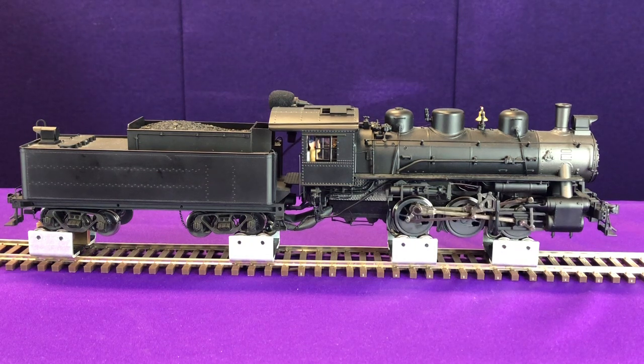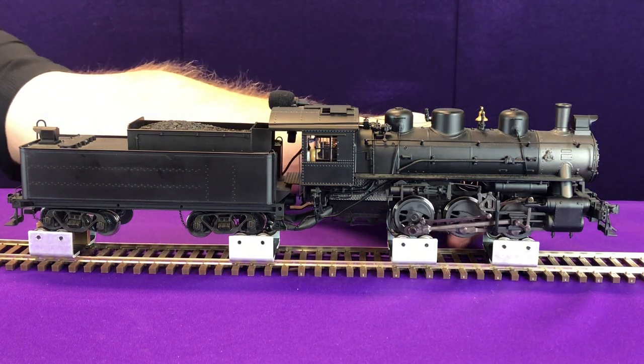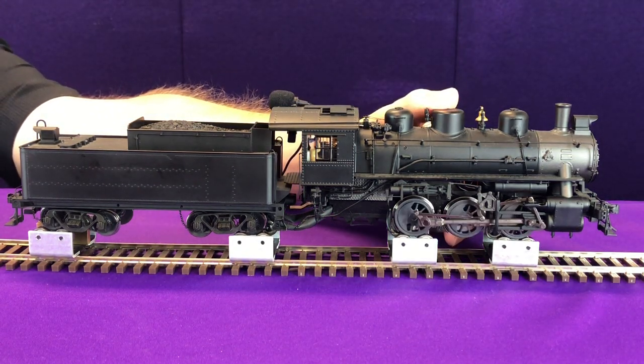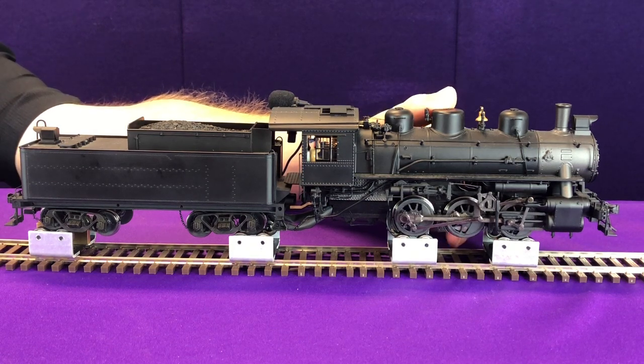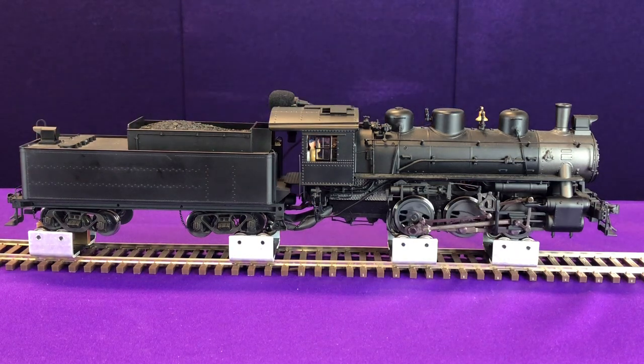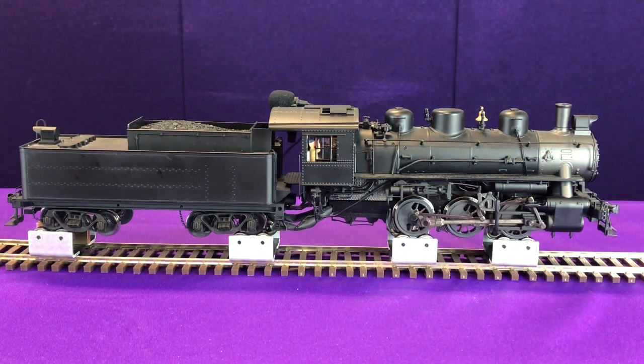And once we're at speed step 10, you kind of hear the chuff back off. But now again, I'm going to put a little resistance on the wheels, and you can kind of hear how that chuff is changing and getting louder. And then when I release, you can hear that chuff back off. So this is how we set and calibrate the dynamic digital exhaust. I definitely encourage you to do it. However, I will say on our steam decoder, it is set up out of the package so that you can enjoy the dynamic exhaust right away.